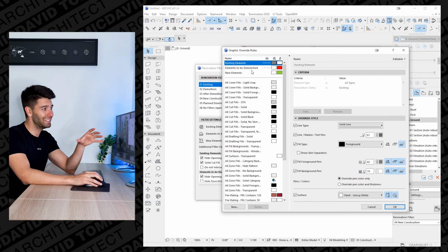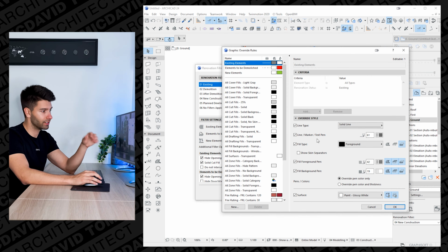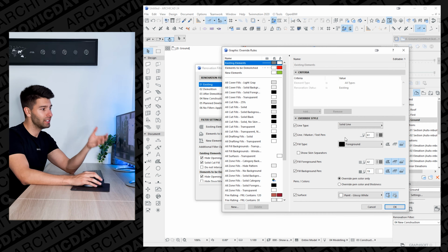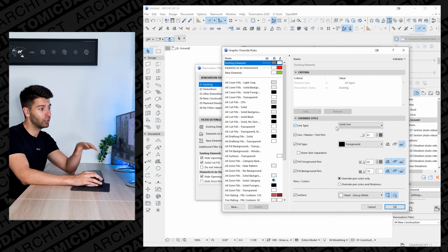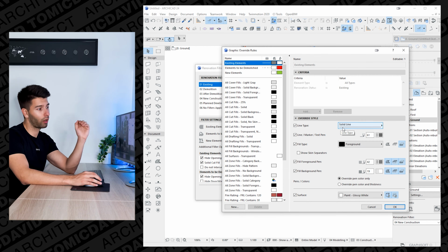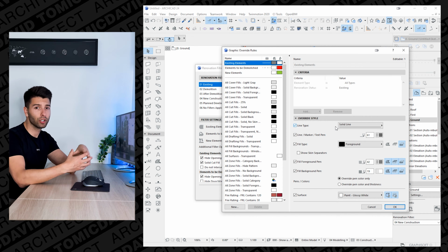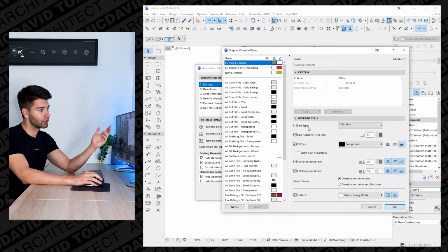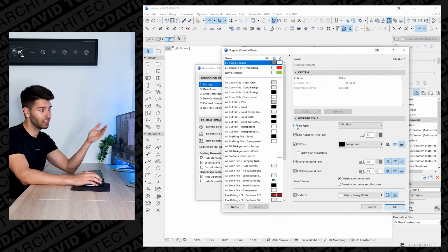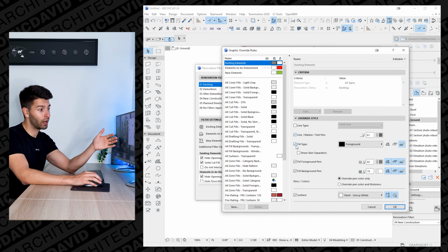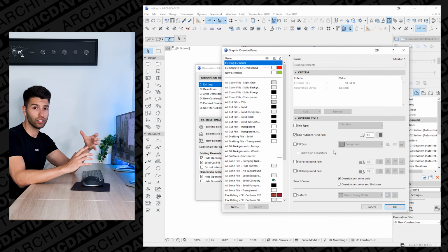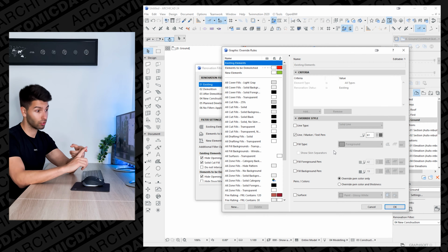So we're talking about existing settings here and existing elements. The default on here is all of these settings, which I haven't changed from the template. Personally speaking, I do like to use the gray, but I don't like to preference all the line types to turn to solid. Sometimes you need the dashed lines to clearly indicate what things are. So in my personal experience, I usually untick line type, keep line marker on, and untick everything else in that palette. So we're just changing all the blacks, blues, greens to grays.